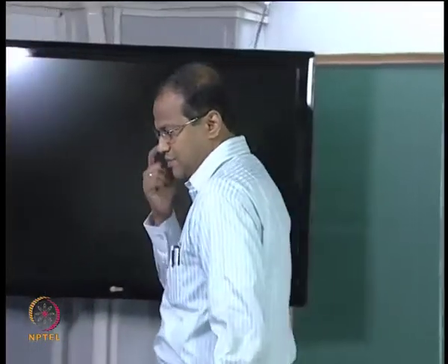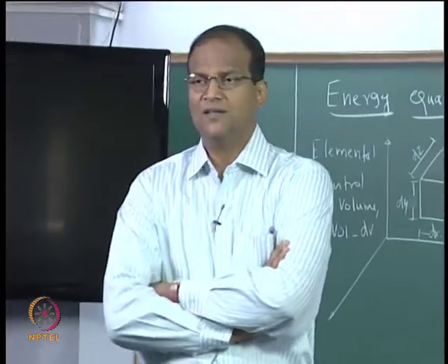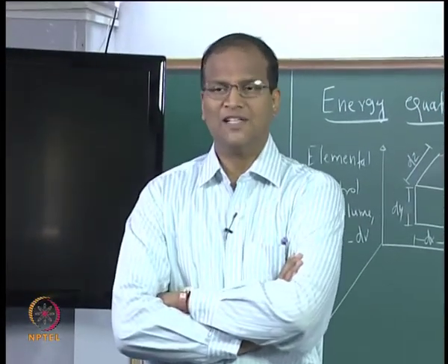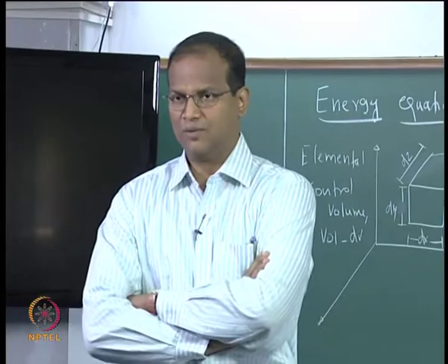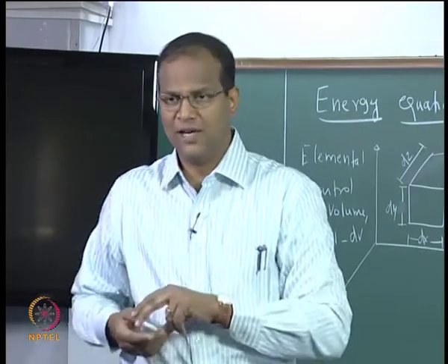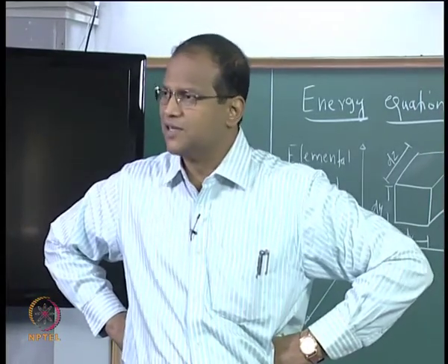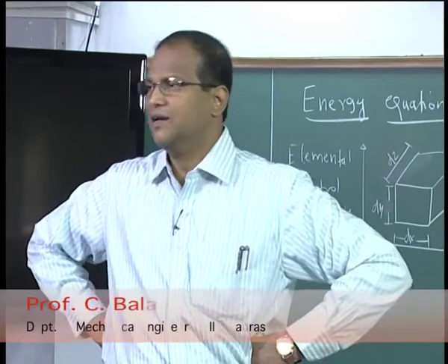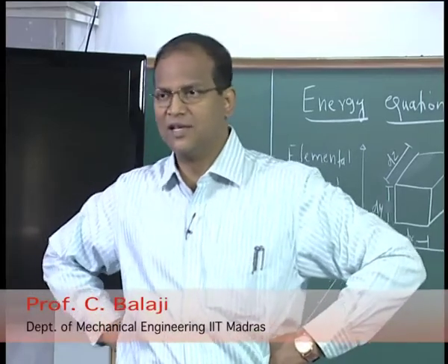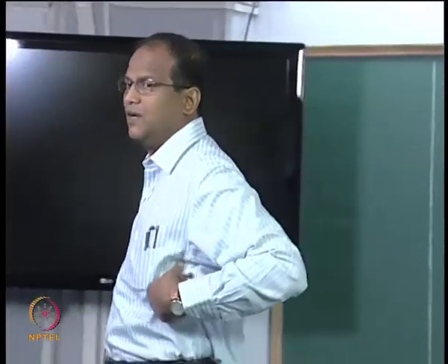So, in today's class we will go through a very important derivation for conduction, namely the derivation of the general energy equation for heat conduction problems. Then you can look at simplifications of this general equation and arrive at the energy equation for one dimensional steady, two dimensional steady, one dimensional unsteady, two dimensional unsteady. This is basically applicable for three kinds of coordinate systems: Cartesian coordinates, cylindrical coordinates, spherical coordinates.